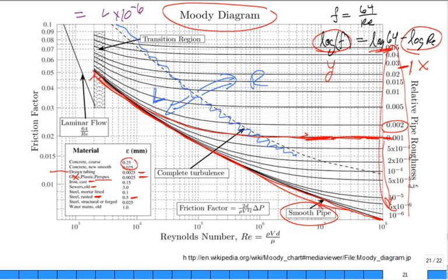Well, let me do this. At the end of last chapter, we talked about Reynolds number independence. Remember that? Here, I'm going to ask you, to the right or to the left, one of these functions has been simplified. In general, the friction factor is a function of the Reynolds number and the relative roughness.